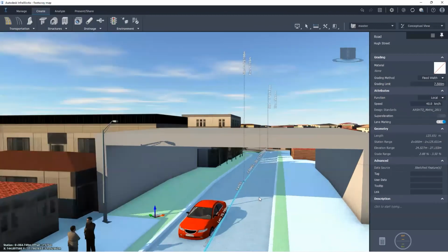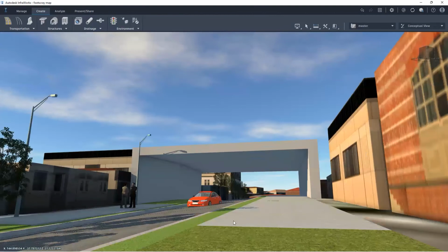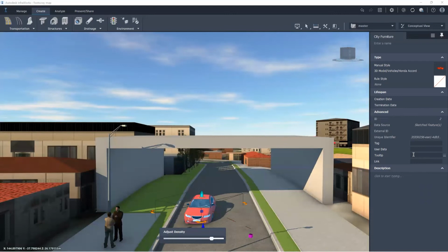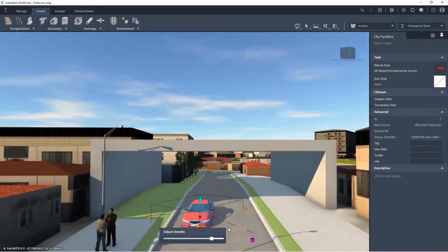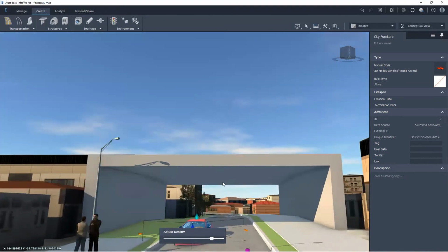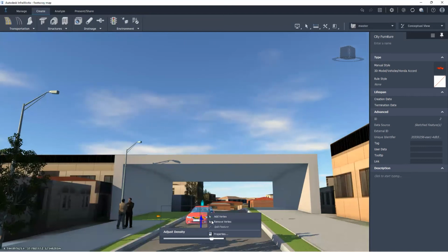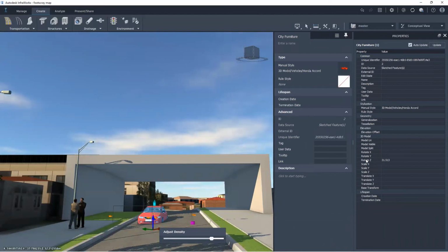It's really easy. But the thing with the 3D models is they don't have the slope. As you could see from the dialog box, you could not actually add slope to the 3D models. So what you could do is right click on the cars and click properties, and then they would show up with the rotate and the scale of the car.